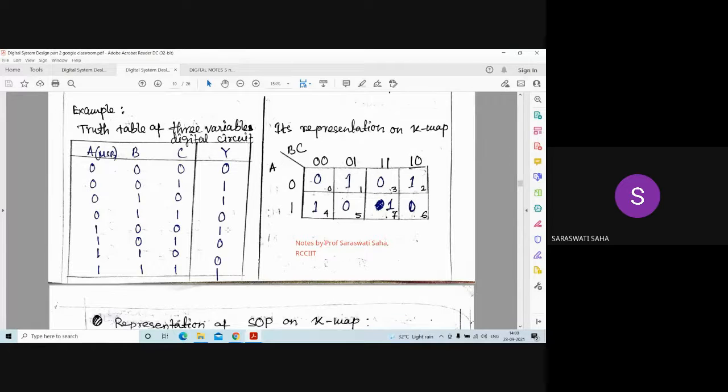Because min-term means we are taking the 1 as a true output of the circuit. So for 4 input combinations the output will be 1, and for the other 4 combinations the output is 0. First identify for which min-terms the output is 1. You can identify it easily because it corresponds to the decimal 0, 1, 2, 3, 4, 5, 6, 7.